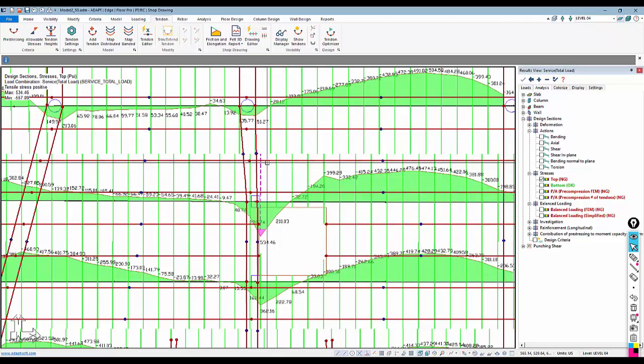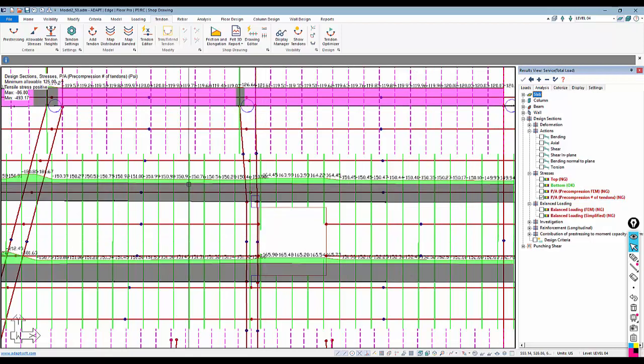So if we wanted to modify these two cables, we then would say, well, is the precompression going to be affected in the sense that it's going to be too high? It's going to cause a precompression of over 300 if I add more post-tensioning to these two cables. In other words, increase the force. And I would come back and just look at the precompression.